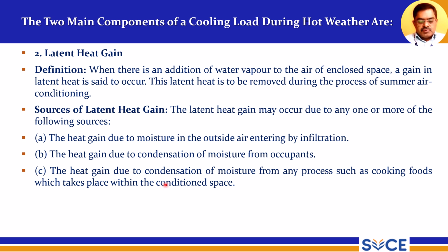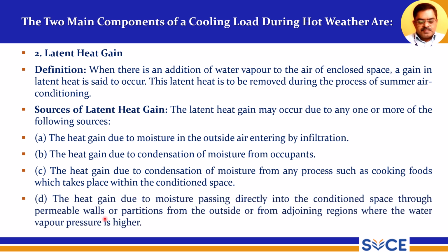The heat gain due to condensation of moisture from any process such as cooking foods which take place within the conditioned space. So even when cooking is happening inside the confined space, there will be humidity, or we can say the latent heat will be liberated, and the heat gain due to moisture passing directly into the conditioned space through permeable walls or partitions from the outside or from adjoining regions where the water vapor pressure is higher.